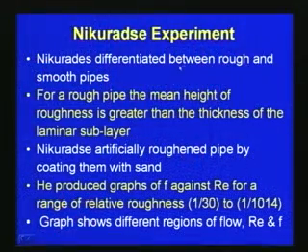And then, in the literature, some of the other important relationships are given by Nikuradse through his experiments. He also produced some charts with respect to the head loss and the friction factor by relating them to the Reynolds number. Nikuradse conducted a large number of experiments for rough and smooth pipes, of different kinds and materials, and he has shown that for a rough pipe, the mean height of the roughness is greater than the thickness of the laminar sublayer.